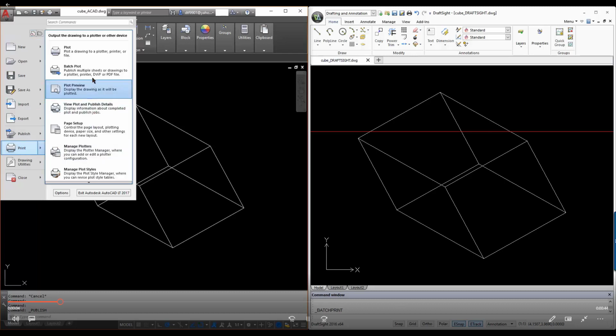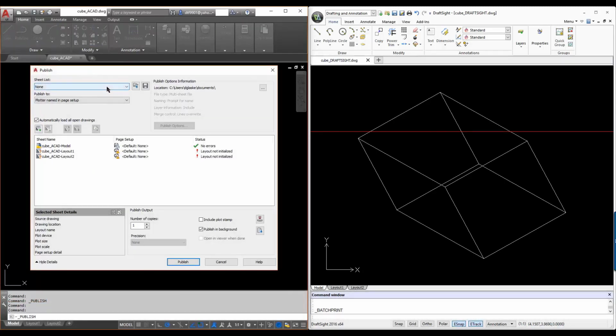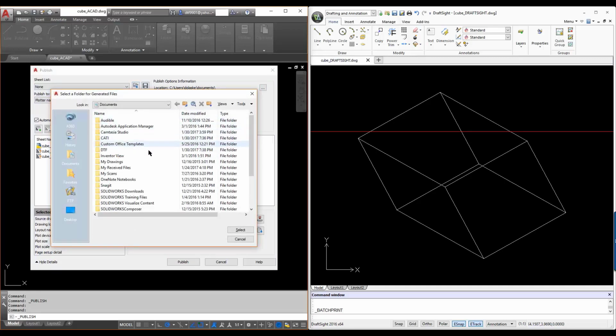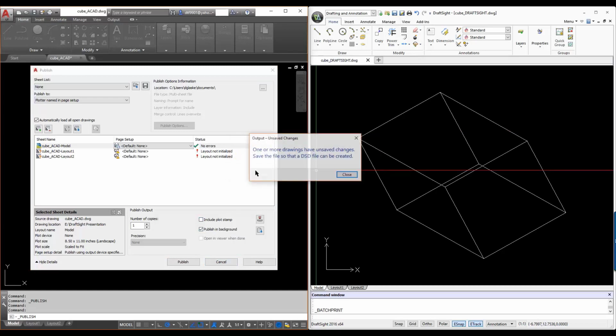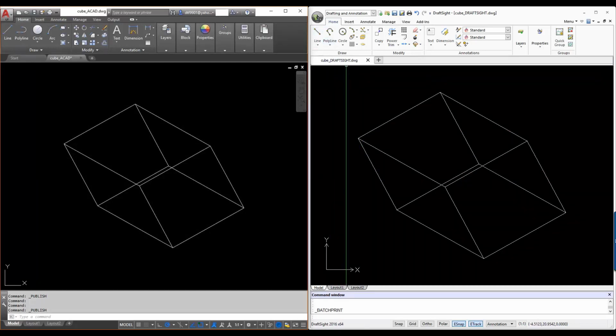So we'll see on the left-hand side we have AutoCAD. We're going to batch print. We're going to say batch plot out here, and we can pick different page setups. We can open to load a sheet. We also can go here to drill to a location that we're looking for. We also can select the certain ones that are inside here. We can do number of copies, plot stamp, create a list, do all that we want to here.